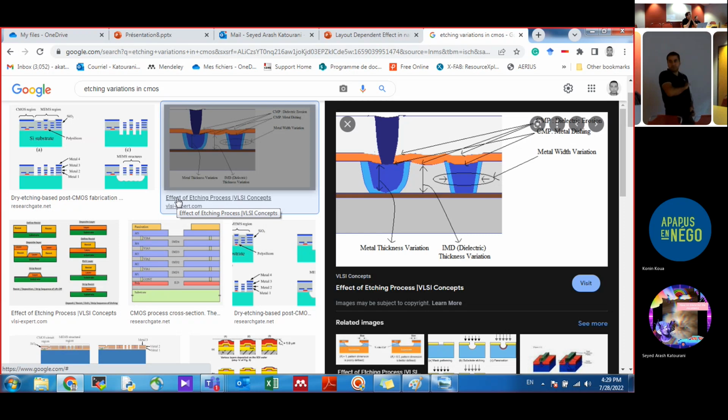Exactly. From my limited experience, I found that the ones on the perimeter were more etched than the ones at the center, probably because they are more exposed. The chemical mechanical polishing is not really parallel and has little angles, so maybe the ones on the perimeter have more chemical etching and mechanical etching.